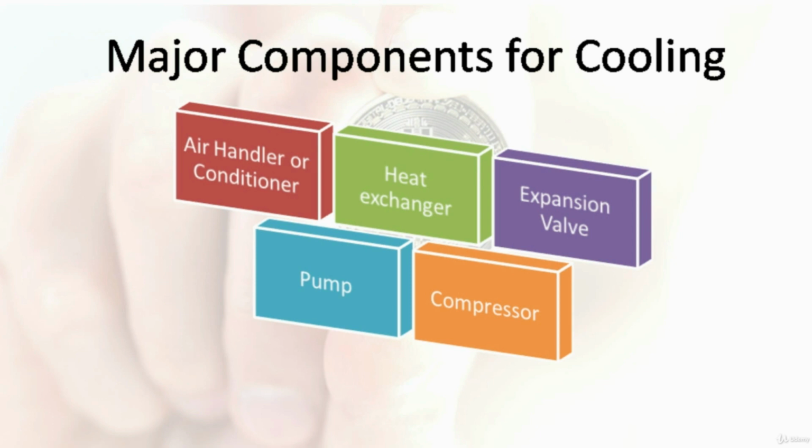Depending on the type of cooling system that is deployed in your mining facility, numerous forms of heat exchanger can be used. Then there is the expansion valve. The expansion valve eliminates pressure from the liquid coolant to allow the evaporator to extend or shift its state from a liquid to a vapor. Although the liquid refrigerant exiting the expansion valve is cold, the high-pressure liquid refrigerant entering the expansion valve will be hot. Inside the valve, the orifice does not expel heat, but rather it lowers the pressure.